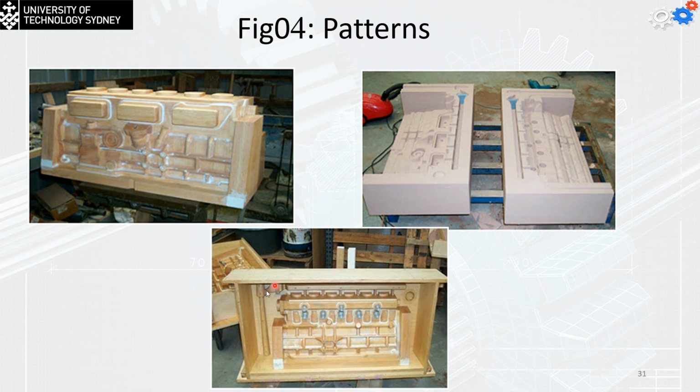By the way, we have two halves here. One is going to do each side of the mold, drag and the cope. We take them out, we're going to have these details, and then we're going to compact them together. Now, this one was dried, and this will replace the process of adding the metal jacket to protect the part from failing.